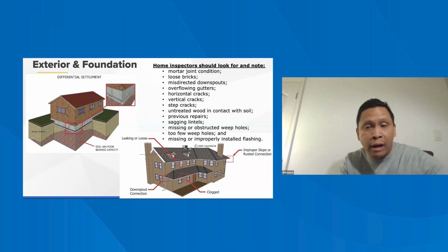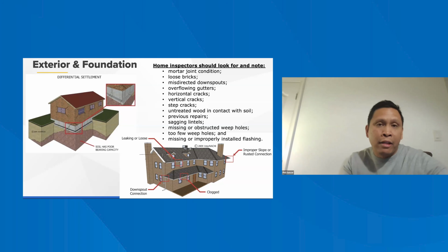I've actually seen cracks that are an eighth of an inch that allow water to transition through. Now, not foolproof, but where is the greatest probability for cracks to actually transition all the way through the wall? The greatest probability is in weak points in the foundation. Weak points in the foundation would be things like large openings, windows, doors, beam pockets. Those are openings in the foundation where that can happen.